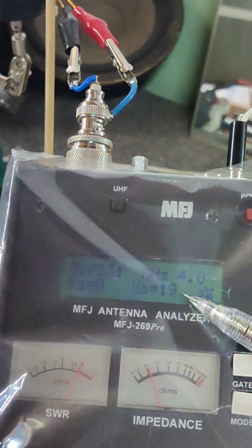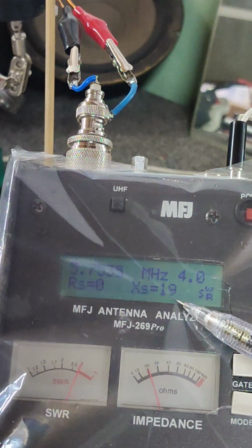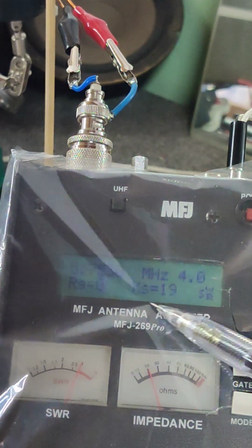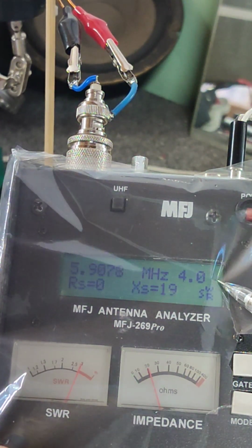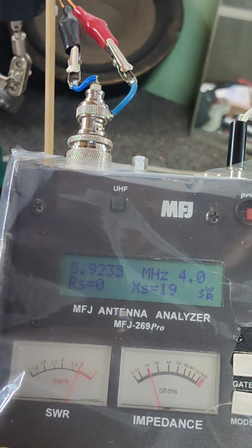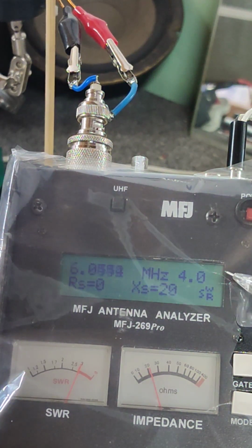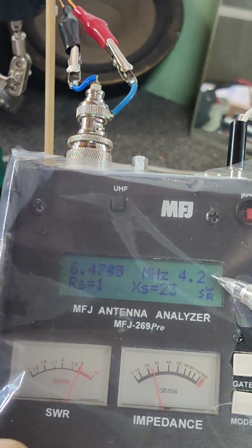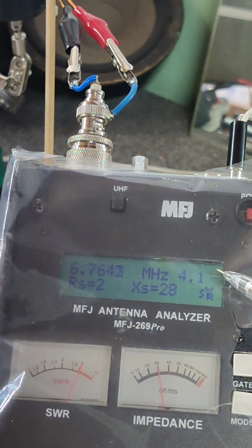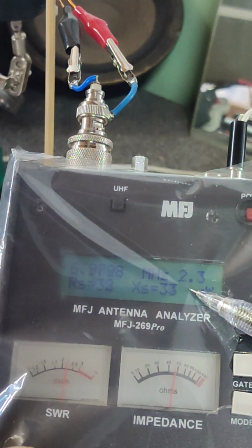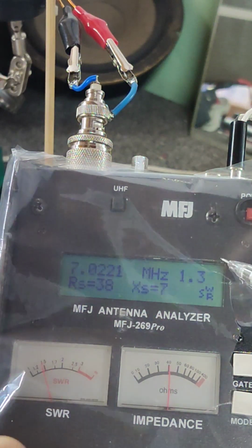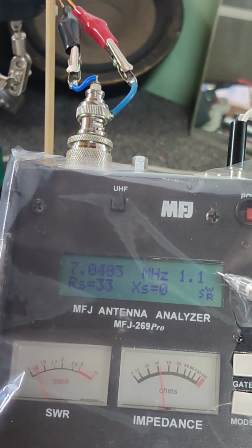Again, we need the smallest SWR, and of course the XL must be as small as possible. Specifically SWR, that is the main thing that we must look for. Now I keep on sweeping. You can see we reached 6 megahertz, 6.1, 6.2, 6.5. Okay, 6.7. You can see, aha, it's going down. When this is going down 2.3, we go of course to the lowest point, 1.2, 1.1. Let's see if we can go to 1.0.